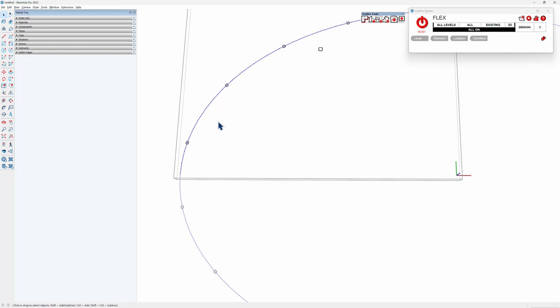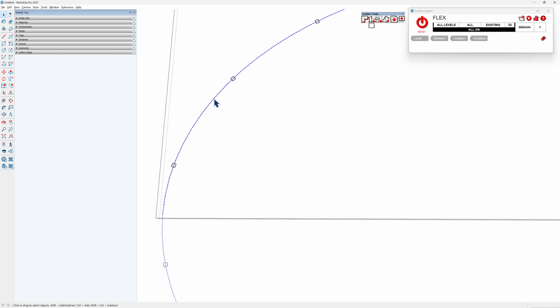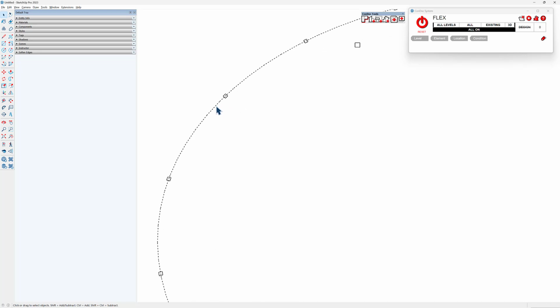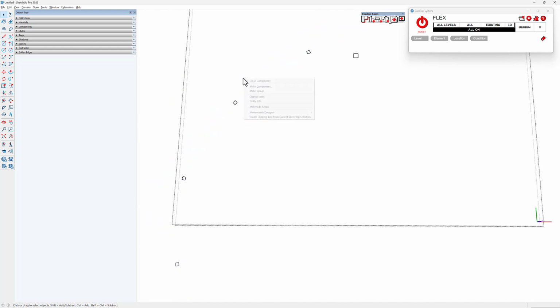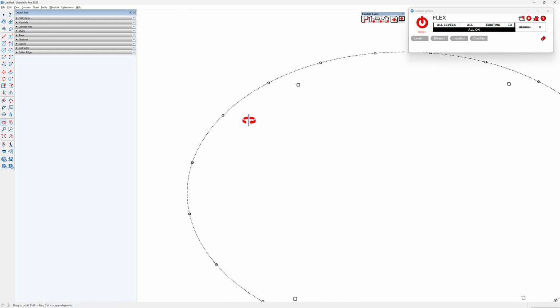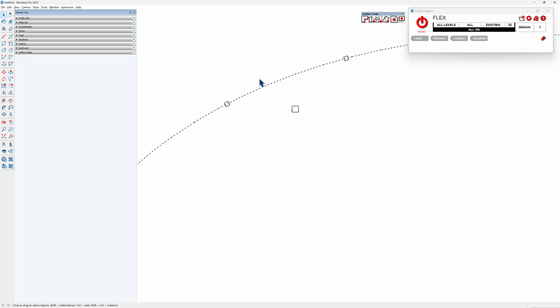And then with the dashed lines, I always like triple click them and make it into, yeah, it's okay, I don't need to make that into a group. The reason I typically make them into a group, and I believe that the other DP Line Styler works the same way, is that you can accidentally unhide, and then that kills your dashes, all right? So I'm gonna undo that. I'll cut it, I'll choose make group, I'll paste in place, and now I've got that perimeter line around the outside.